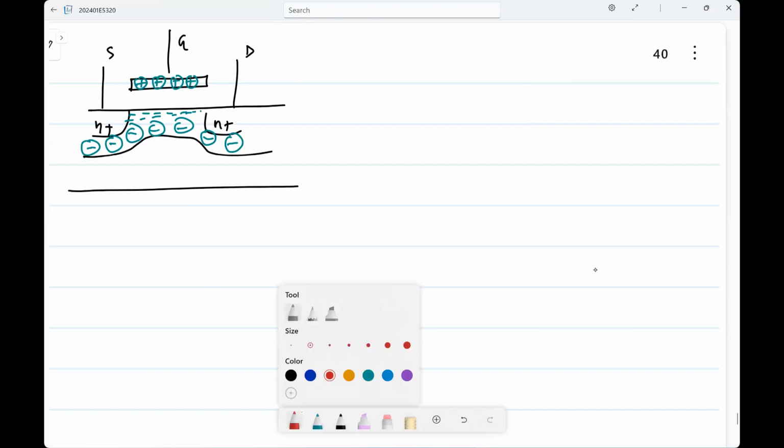Now, again, we'll only look at the results that are relevant for us. On this oxide semiconductor interface, there can be trapped charges. I'll just show that as some charge traps. If you have those charge traps, the charge balance should include those as well. Earlier, without any of that, the inversion layer charge plus the depletion charge should be equal to the gate charge. Now you have these interface trap charges also, and they will also come into the charge balance equation.